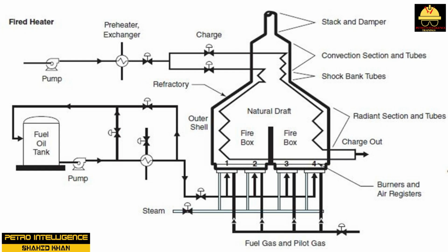This control takes place as the fuel and primary air mix at the burner and is enhanced by adjustments on the secondary air registers mounted on the outside of the burner. An oxygen monitor carefully tracks the composition of the hot combustion gases.